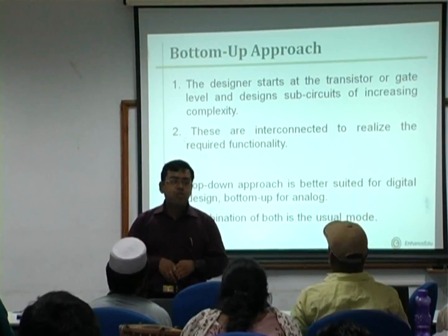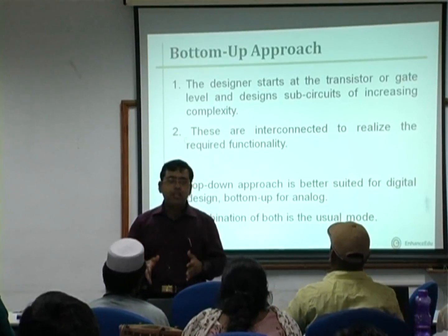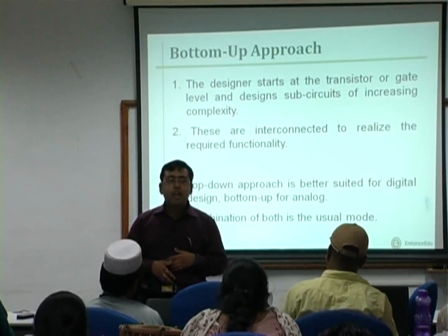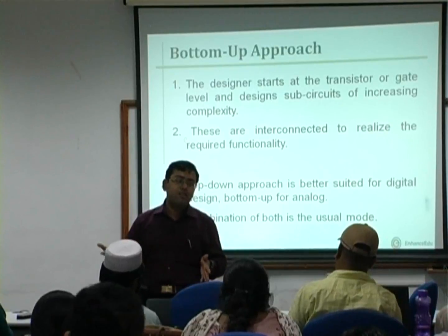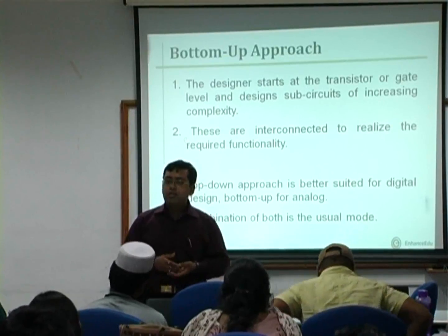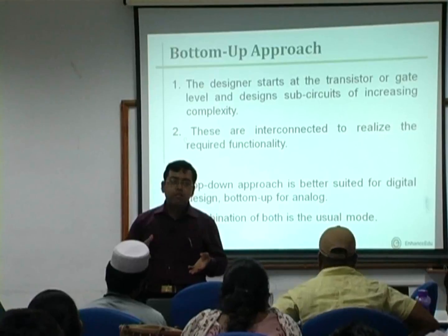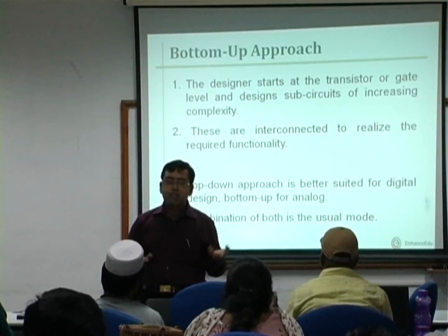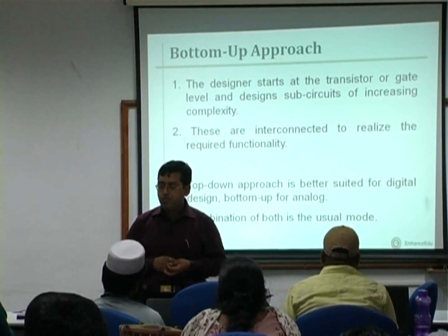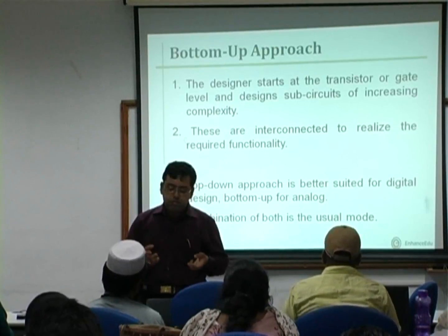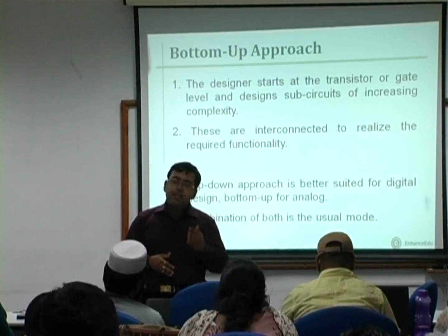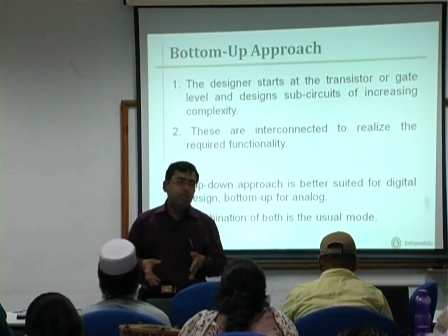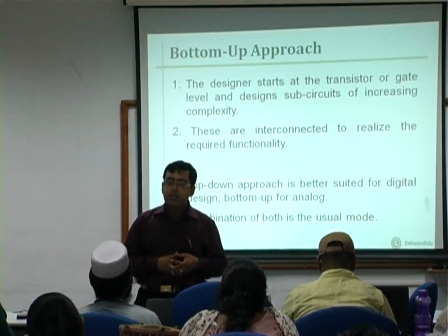So accuracy is not that much needed, although it is not really true from the perspective of 2011, because now the VDD has come down to as low as 0.6 volts, so that means you have only a range of 0.3 volts or 300 millivolts for logic 0 and 300 millivolts for logic 1 or so. So again, people are rethinking whether they should use bottom up design in digital systems design.